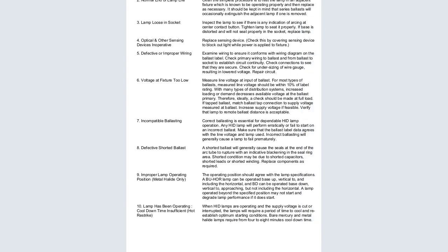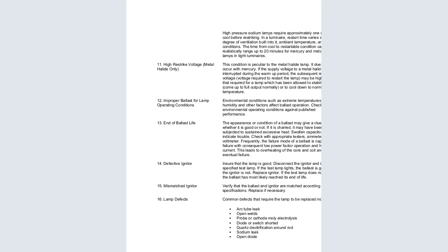Another cause can be that the lamp has not cooled down, giving insufficient hot restrike. When HID lamps are operating and the supply voltage is interrupted, the lamp will require a period of time to cool and re-establish optimum starting conditions. Bare mercury and metal halide lamps require from 4 to 8 minutes to cool down.